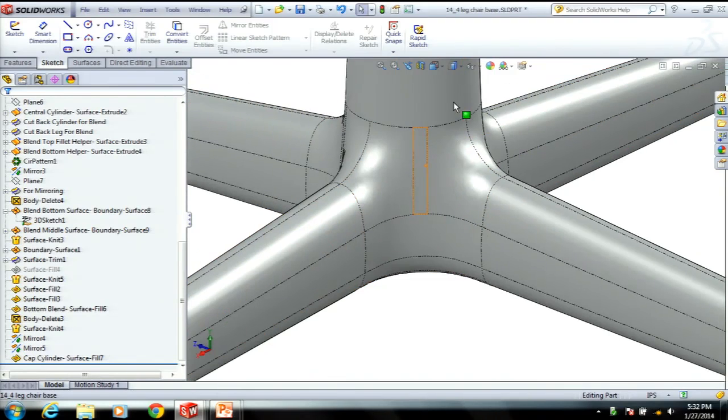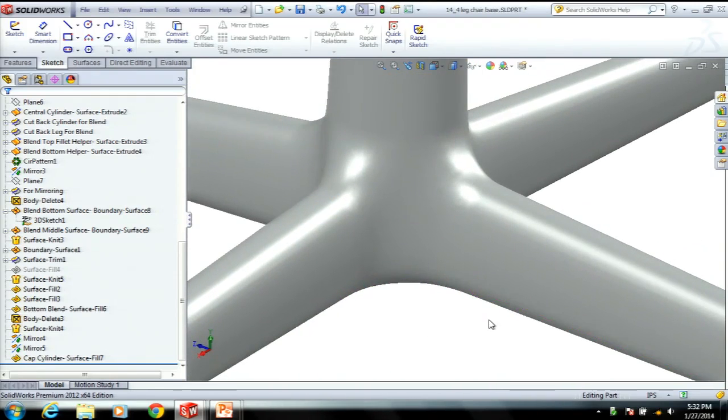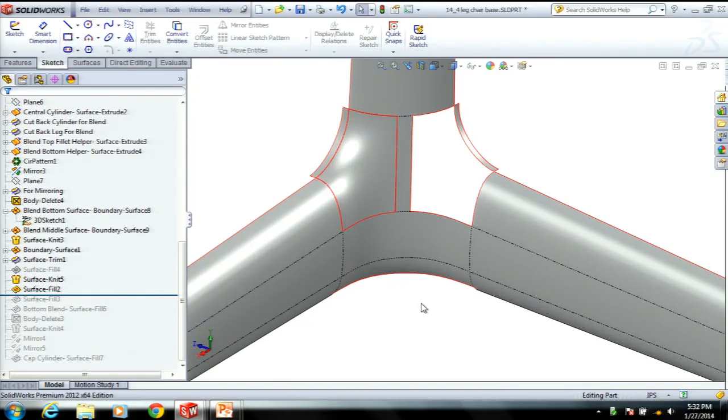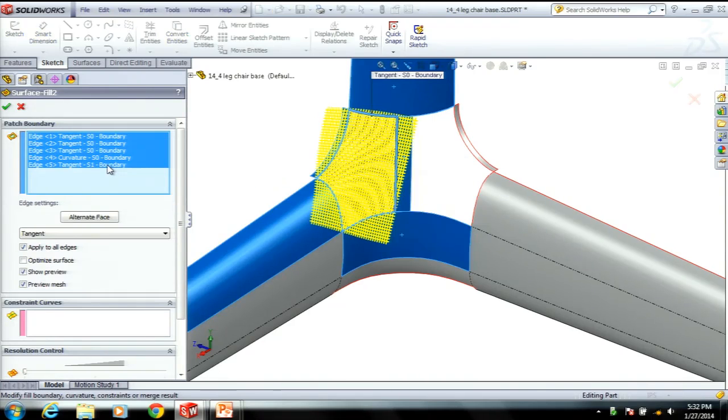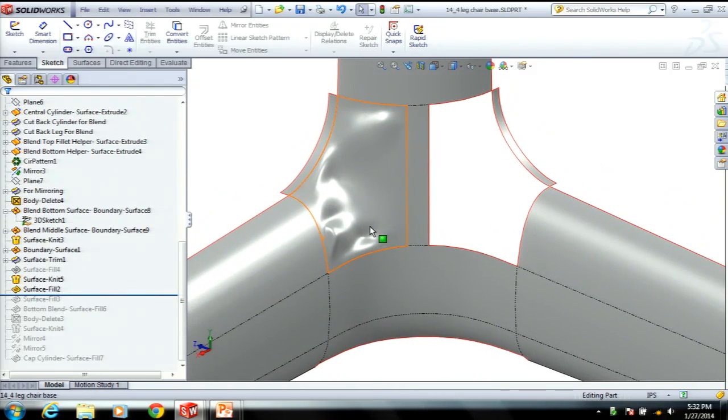Then finally, after mirroring, let's turn off our line. We see everything's nice and clean. One thing to be aware of, especially when doing this curvature continuous kind of modeling, is a lot of people might just say, well, let's apply curvature to everything. That's the best, right? So apply curvature to all our edges. Wow, we have that kicked in, dented surface fill again.